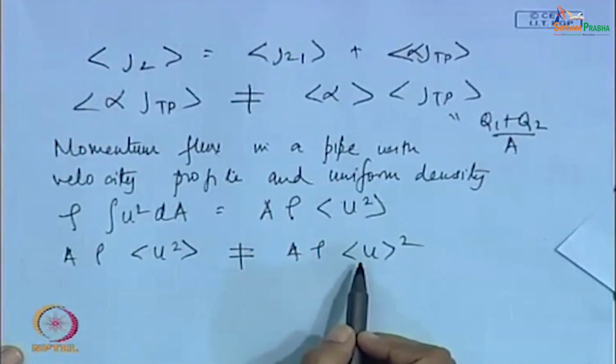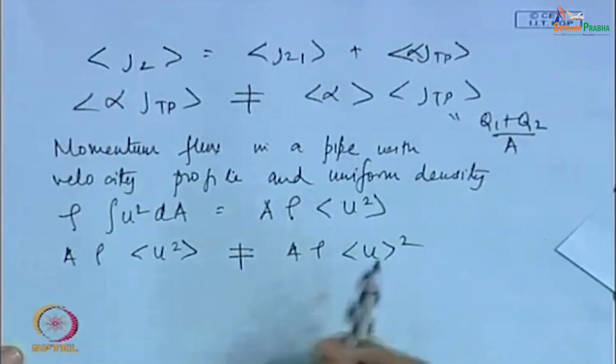If you remember, this was the exact thing which we had done in Bernoulli's equation. The basic equation is just u square by 2 plus gz plus delta p by rho plus delta u square by 2, and then we introduced a correction factor alpha there, is it not? The alpha was the kinetic energy correction factor. Why did we introduce it?